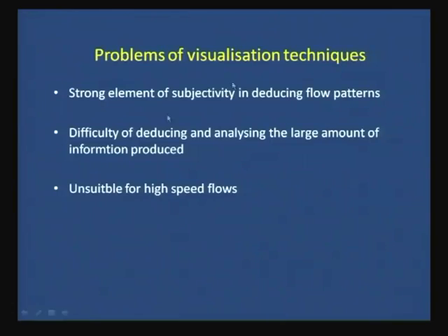In this particular slide, I have just written down the basic problems which all of us know. The first thing is that the flow generally occurs at very high speeds. When they occur at such high speeds, it is very difficult to distinguish between the two phases. Particularly for annular flow and dispersed bubbly flow, you will just find something is moving through the passage. It is very difficult to apprehend whether it is a bubbly mixture moving or whether it is a gas core with entrained droplets and a liquid film moving. It is very difficult to differentiate.